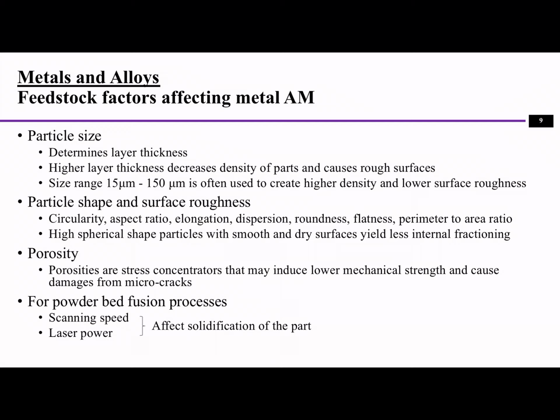But for some applications, it might prefer porosity. For example, when we are making implants, right, using metals to build those implants to use as a bone, because the bone has a lot of porosity as well. So there's a fusion process when we put an implant into the body, and the bone will actually start to grow inside those.